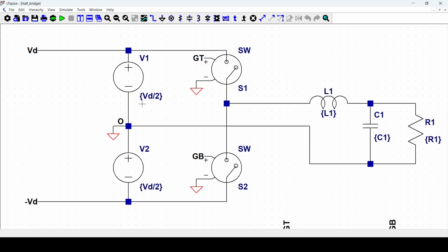In a real design, we would have two real capacitors, but for this example we are assuming the capacitors are large enough to neglect the DC bus voltage ripple. Then we've got two switches that share a common switching node. This node feeds directly to the output filter, and then we will study this circuit with a purely resistive load.